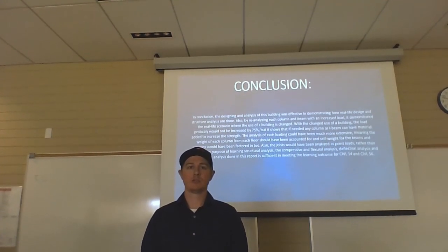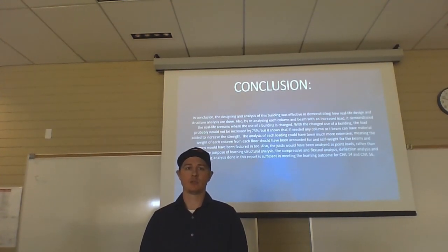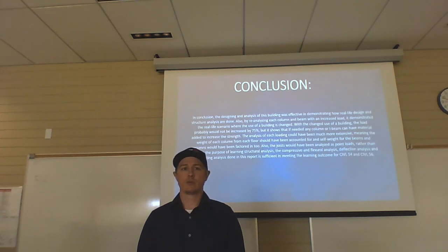So in conclusion, the designing and analysis of this building was effective in demonstrating how real-life design and structure analysis are done. By reanalyzing each column and beam with an increased load, it demonstrated the real-life scenario where the use of a building is changed. With the changed use of a building, the load probably would not be increased by 75%, but it shows that if needed, any column or I-beam can have material added to increase the strength.